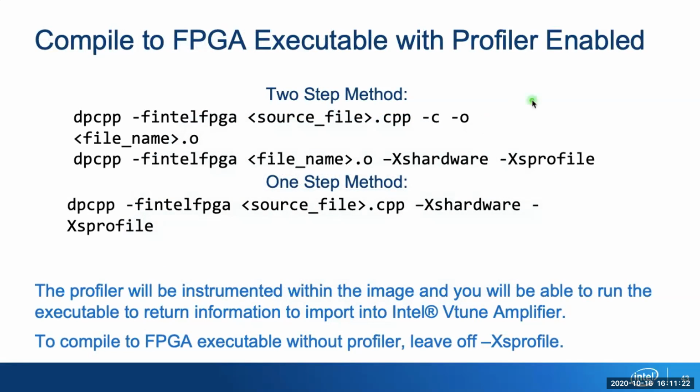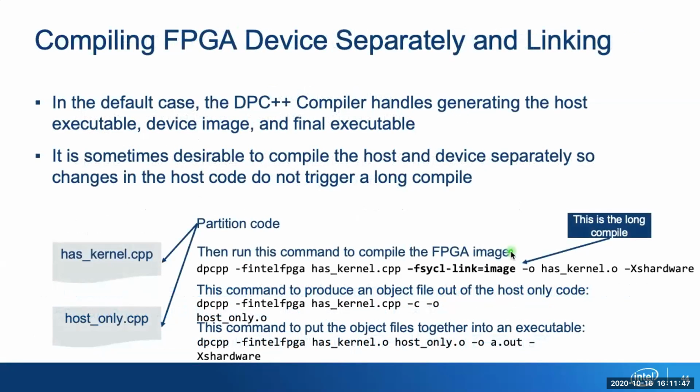When you compile it to FPGA, it's possible to generate profiler-enabled code to work with VTune, like Vladimir just explained. I think the Intel Advisor is not compatible with FPGAs. It's also possible to compile the FPGA device code separately and link, to avoid unnecessary compilations.